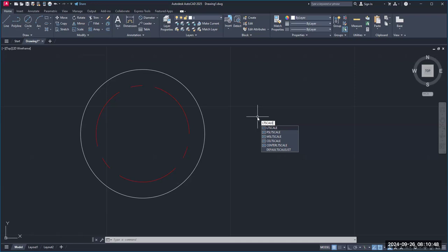All right, so we're going to enter this. And look, it gives us a scale factor of 1. Just change that to 0.25 and enter, and look how your center line looks now. Are you with me? All right, cool.